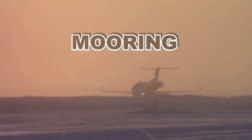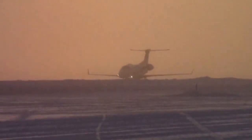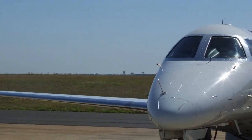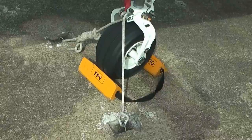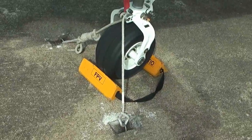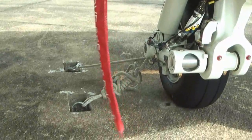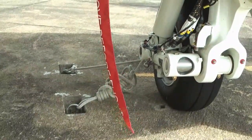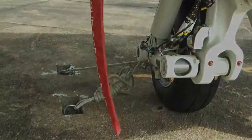Mooring. Mooring is necessary when the weather conditions are bad or unknown. The area where the airplane is to be parked in and moored must be paved and level, with ground tie-down anchors available. Hold the airplane in the parking area with nylon ropes. Attach the rope to the mooring attachment point and attach the anchor with a bowline knot.